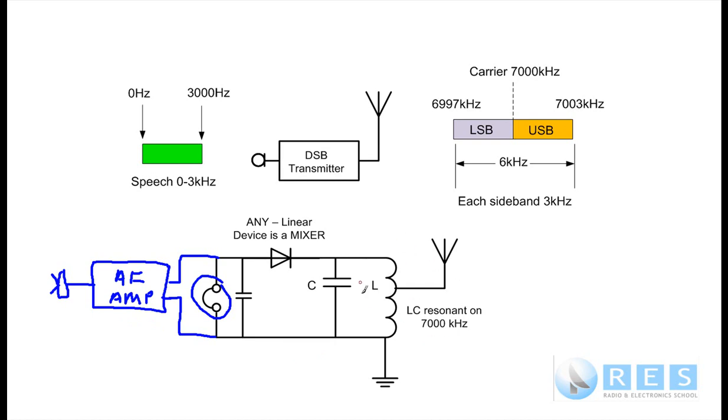I recall from doing this on the broadcast band that I used to use a cardboard tube from a Cool Mint tin, and I'd put, I think it was 60 turns of wire on the Cool Mint tin, and that capacitor needs to go from roughly 30 to 250 picofarads, variable capacitor, airspace capacitor, and that puts this tuned circuit on the broadcast band, not 7,000 kilohertz.